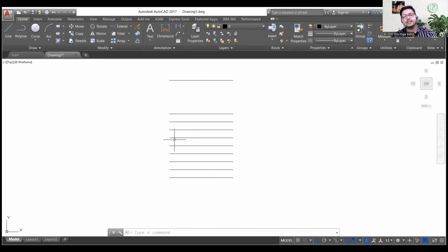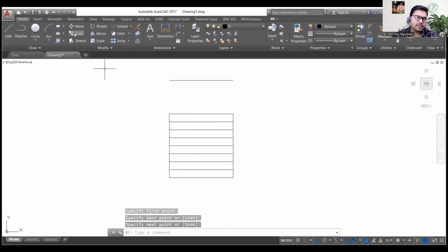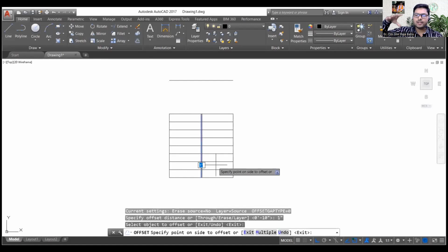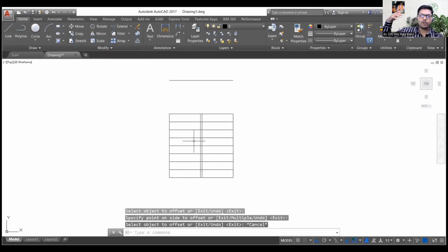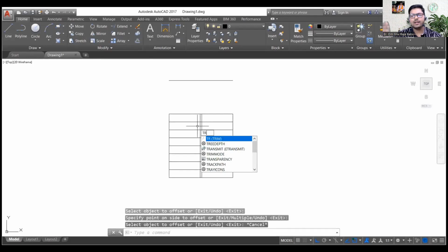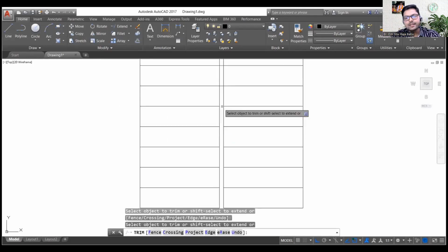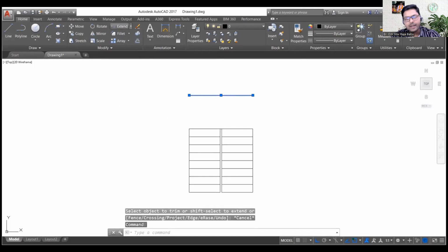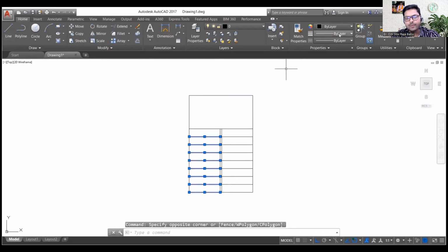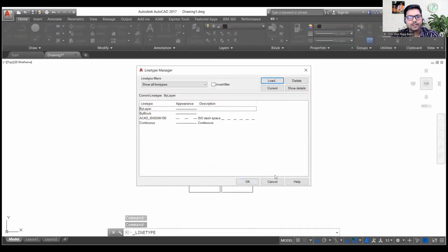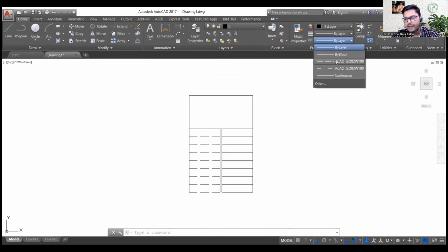Now in this case, our building height is 9 feet. Normally the building height is 10 feet or 10 feet 6 inches, but in this particular case, because this client has budget restraints, he cannot afford too high a building. So wherever he can save the cost, he is saving the cost, so he's keeping the building height as 9 feet. And for the 9 feet high building, or you can say the floor to floor height is 9 feet, I can simply go with 18 steps.